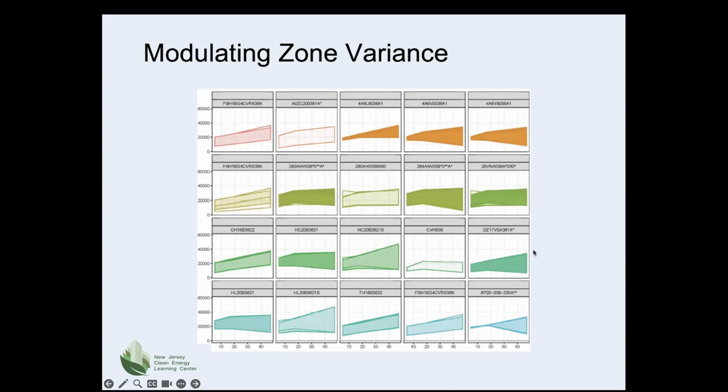So looking up at the top row in the middle, that's an example of a heat pump that has a fairly low turndown ratio. In other words, it can't modulate lower temperatures. The capacity drops off fairly dramatically compared to some others. And that is an example of one. And this one is an example of the same thing.